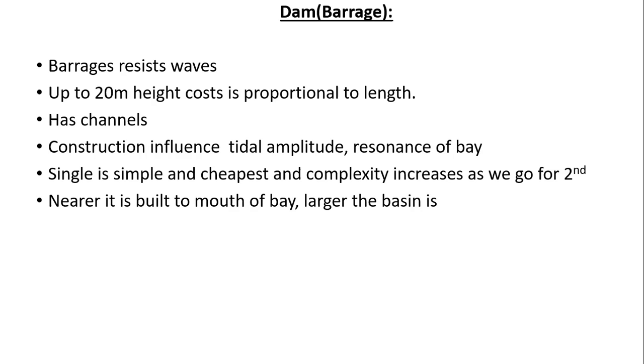These are available. The location of the barrier is most important, because the energy available is related to the size of the basin and to the square of the tidal range. The nearer it is built to the mouth of the estuary or bay, the larger the basin will be, but the tidal range will be smaller. There should be a balance between the increased output and the increased material requirements and construction costs. So all have to be balanced.